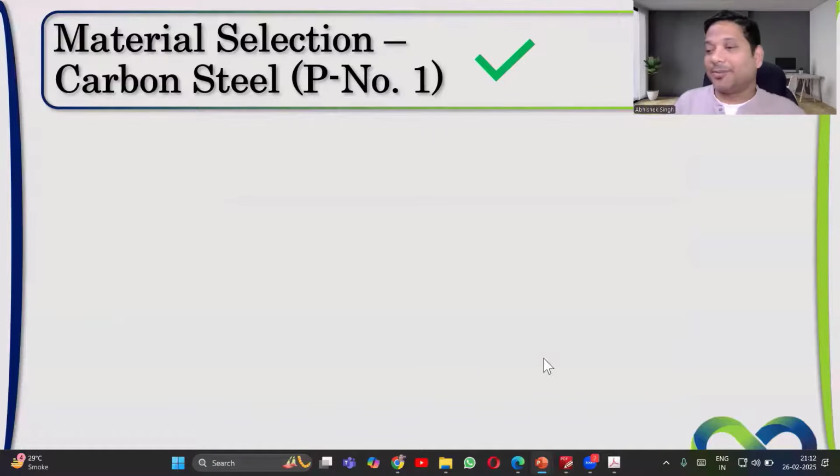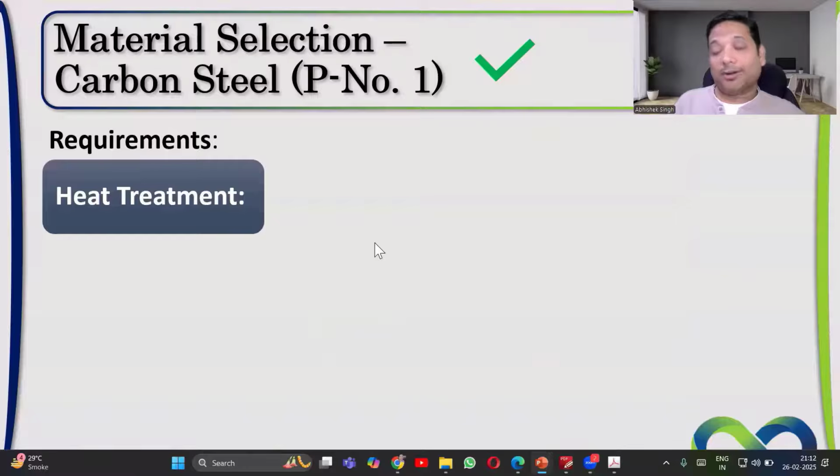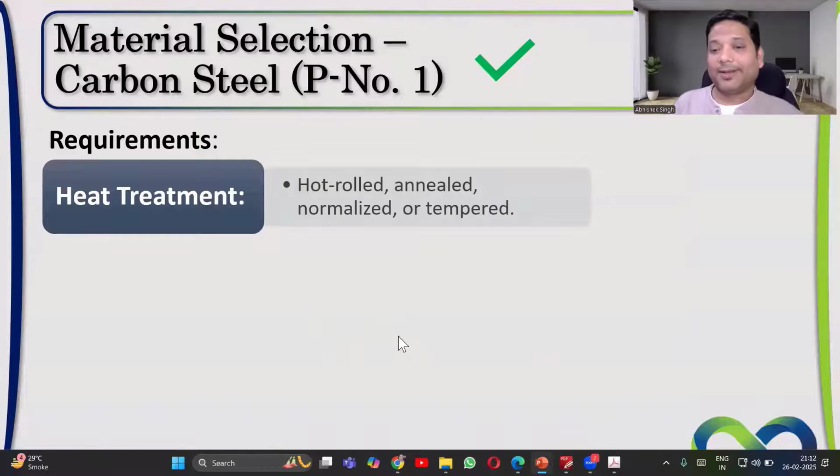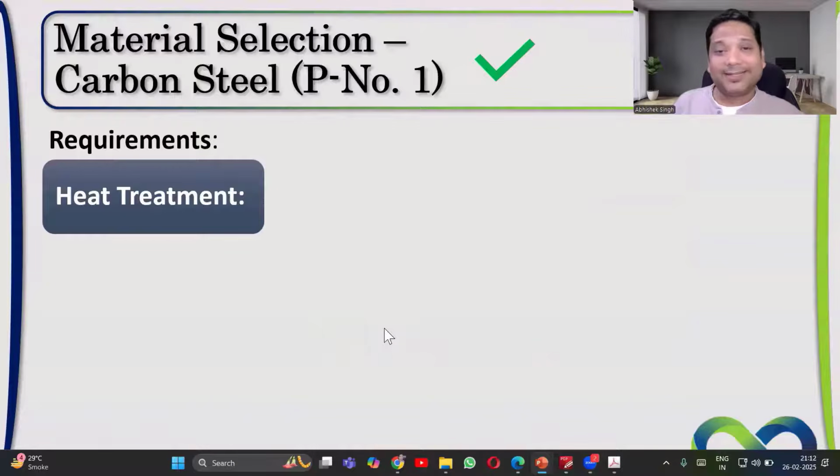Great. Now let us talk about carbon steel, our favorite material. What is the limitation for that? Before the limitation, let us say that NACE 103 has become applicable. If we are going to use carbon steel, what are the requirements which we have to follow? You might have already studied in 175 what are the things which we do. Many of you may be familiar with the criteria which we impose when NACE is applicable, because we have to follow this.